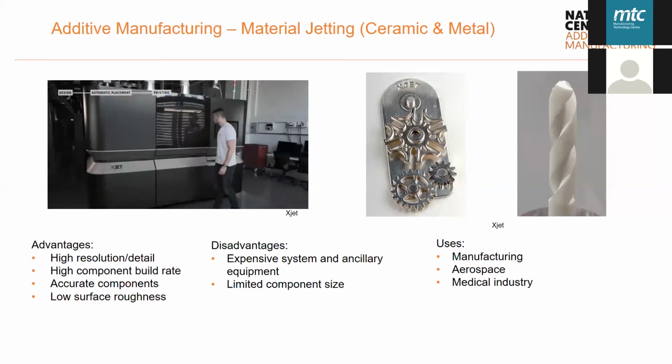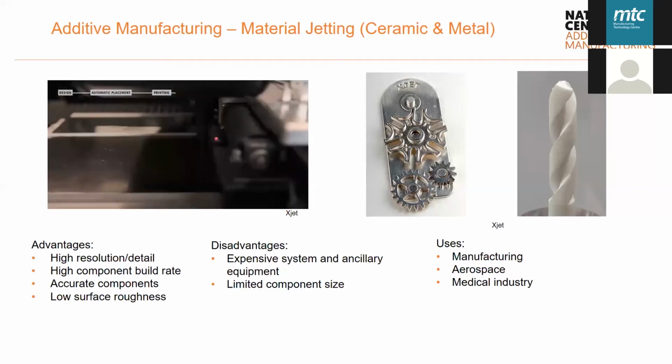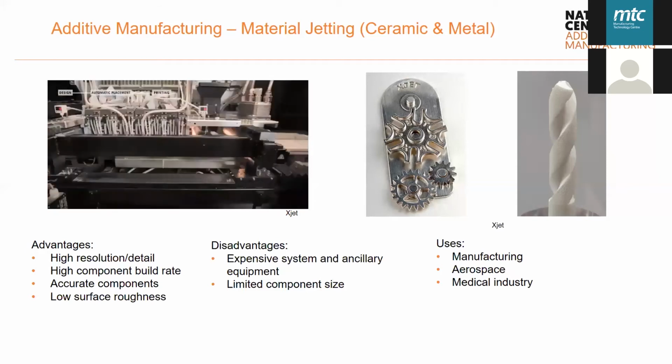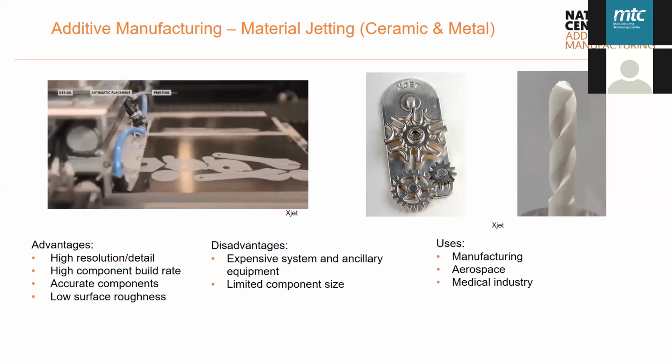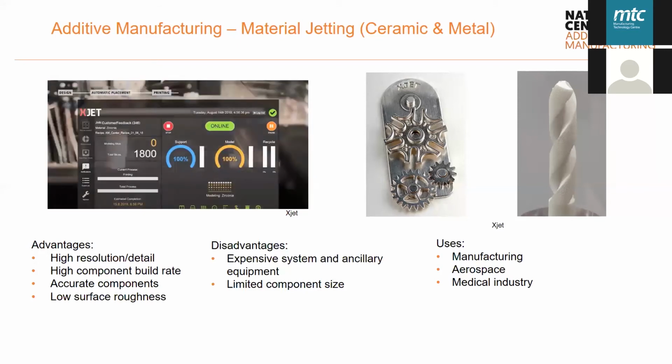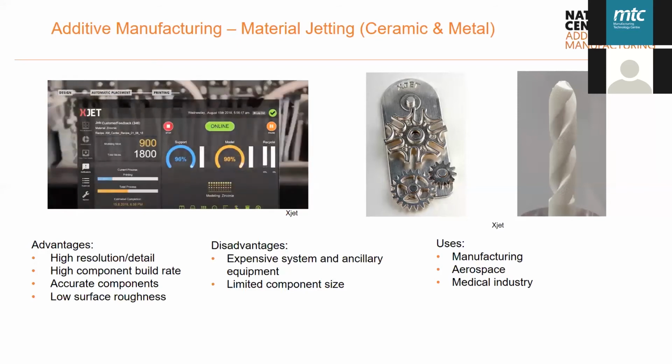There is also a fairly high component build rate for this system, and you can manufacture accurate components out of ceramic and metal. Low surface roughnesses as built as well, again reducing the amount of downstream post-processing required.